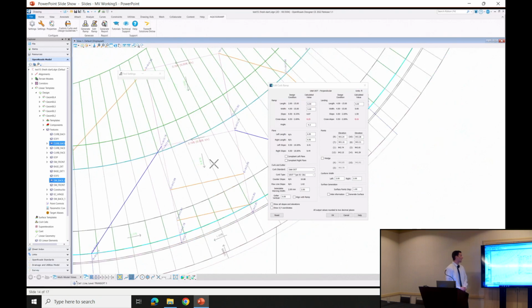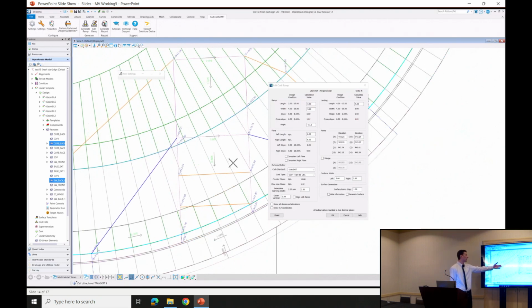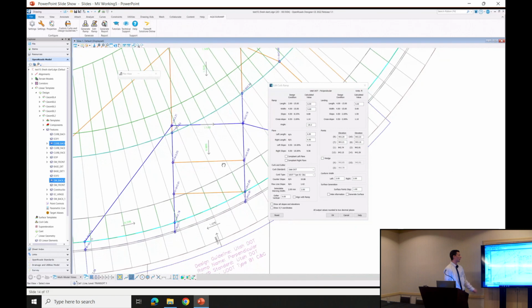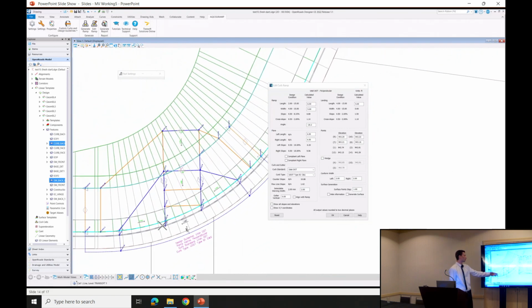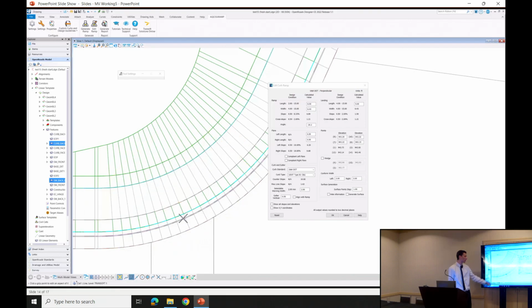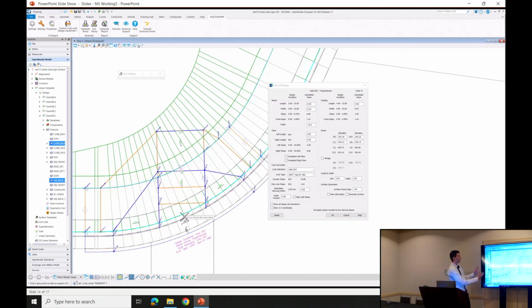And here I'm actually dragging to make sure that the angle lines up with the crosswalk there. Already right off the bat, the slopes are shown in the color green. That means they're compliant. If they exceed, for example, if the flares were to exceed 10%, the label would show the color red. And here I'm just making the ramp a bit wider to align better with the crosswalk.